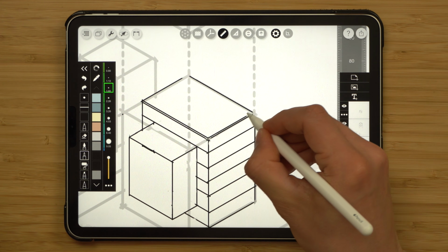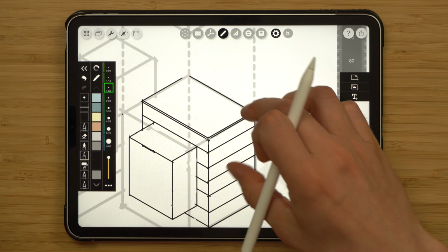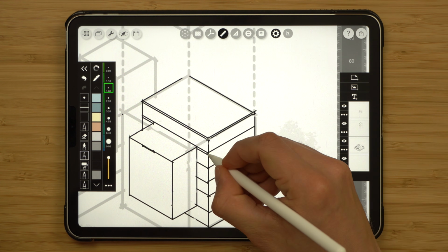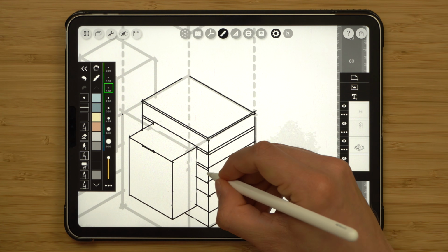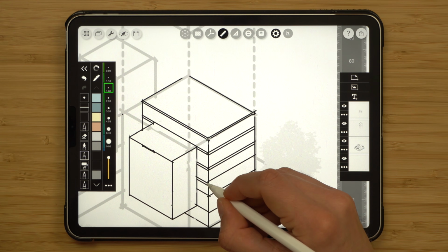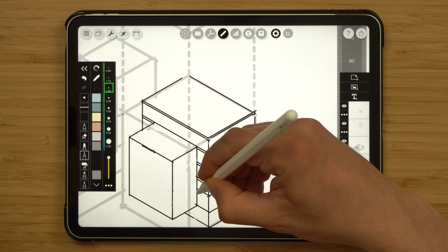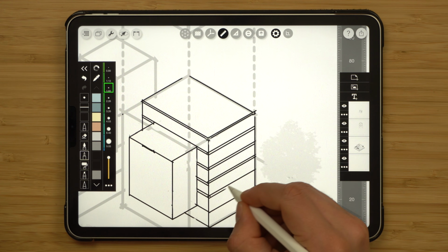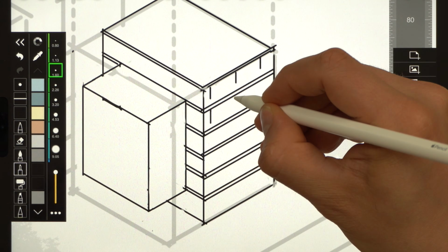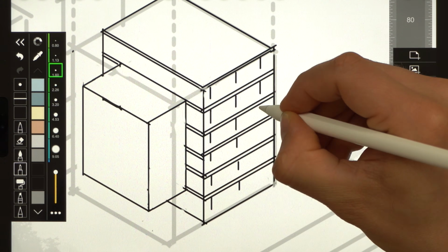So I wanted these floor thicknesses to start on the edge, on the side of the line that would make the subdivisions the same. So I can see some of these divisions are slightly larger than others. I'll pick the side to which I show the extrusion depending on where I want the spacing to equalize, if that makes sense. I can also show the vertical columns that support the building.